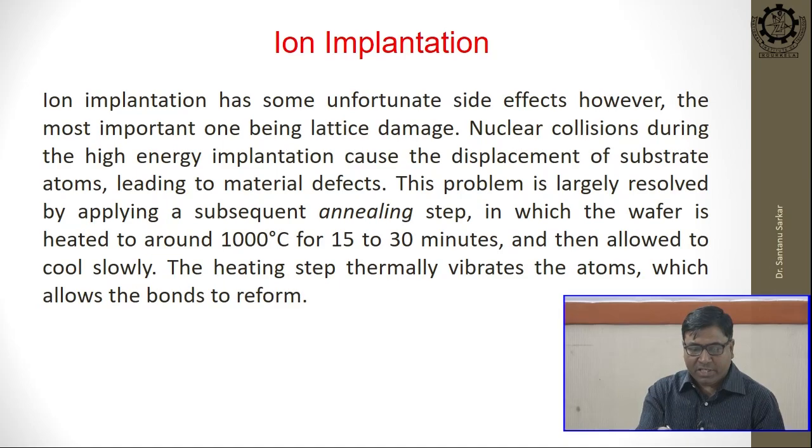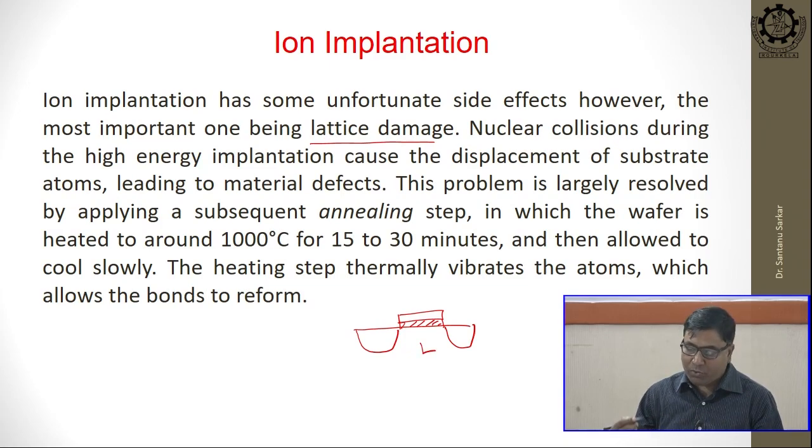But ion implantation has some side effects, like lattice damage, and so many things. So, now you can understand that when we have, say, this is our channel, this is our L, right. Now, what was our original L that we used as a design, and whatever L will be there after the fabrication, there could be a difference, right?